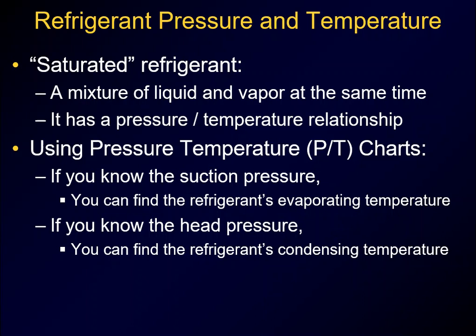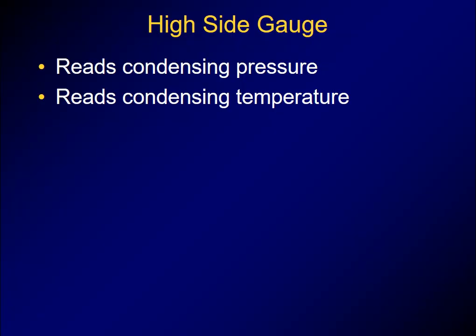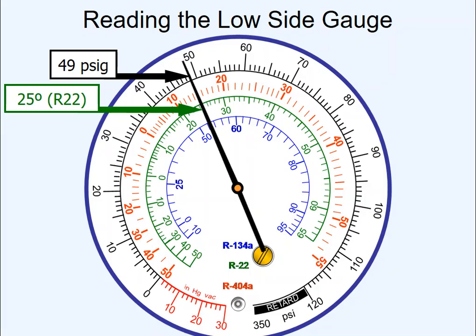So, as I already said, in that evaporator, you're going to have a point where that refrigerant changes from partial liquid to 100% vapor. That point is the saturation point. Your gauges are going to tell you, when you go back to your picture of your gauges, whatever these gauges are reading on your low side, that is your saturation pressure. That's your low side pressure, and then you correspond that with the temperature that it matches up with. So in this case, if it's 25 degrees, that's telling you that this refrigerant at this pressure boils or changes states at 25 degrees.